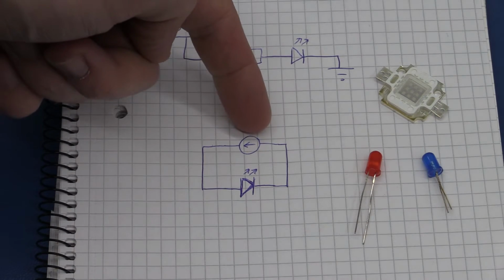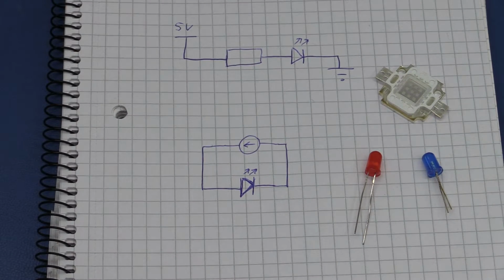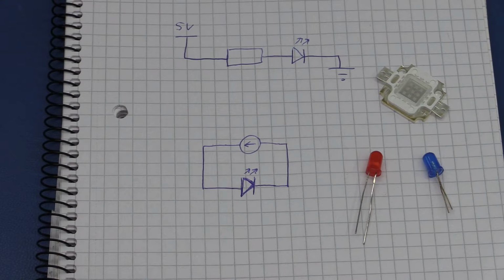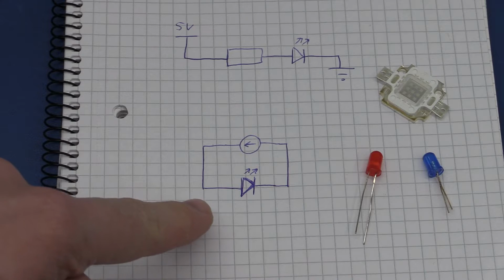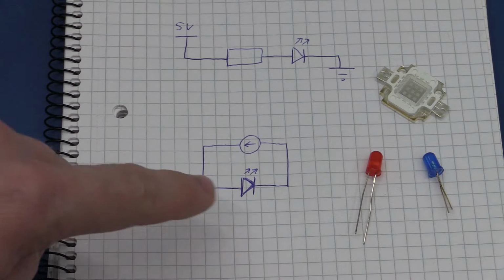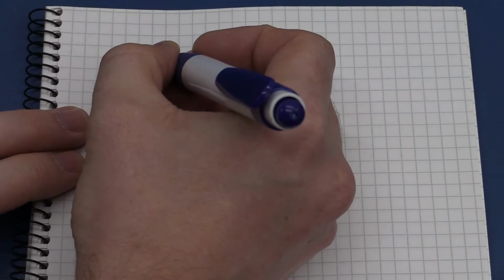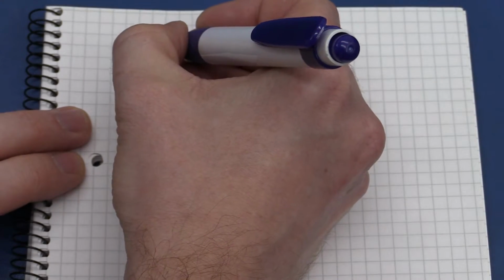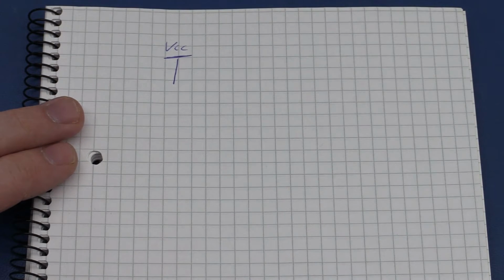And a constant current source we can draw as an arrow. I said in the previous video that we would look at a switch mode constant current supply, and we will indeed do that, but I think it will make sense to include the linear version also. So it's a bit unfortunate for us right now that most supplies come as a constant voltage supply. If you buy a plug pack or wall wart, it will have a voltage written on it, and your batteries will come at a certain voltage. So we have to convert it from a voltage to a current somehow.